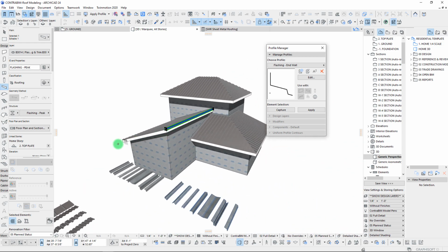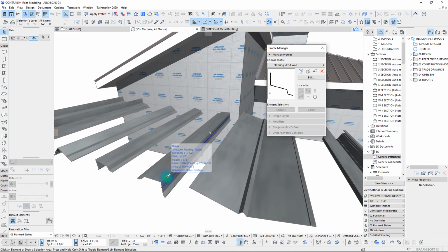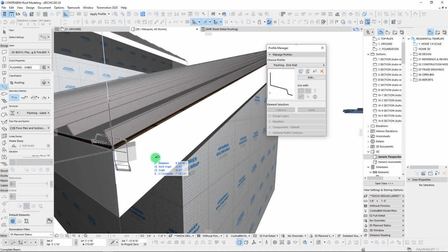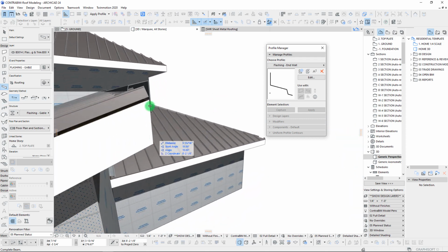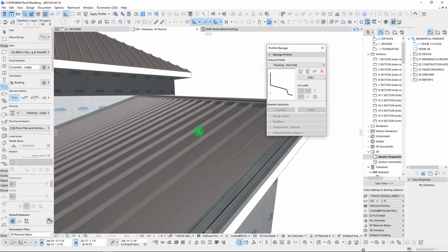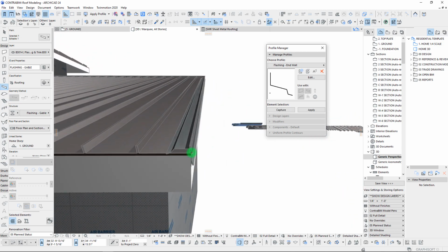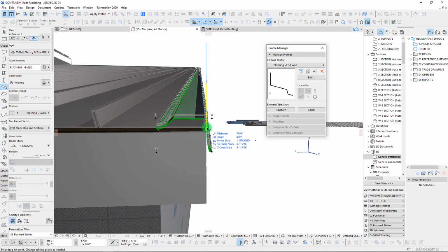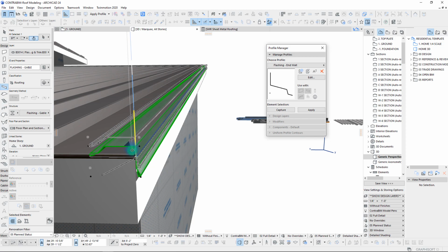Let's work on our gable over on this side. So that's going to be this profile right here. We can start it from down here at the end. It looks like we are pretty close there, so that looks good. We'll take it up to the top, and once again we need to at least elevate it so that we are above that ridge. Kind of tough to see it from that angle, but from this angle you can see right where that's going to hit.